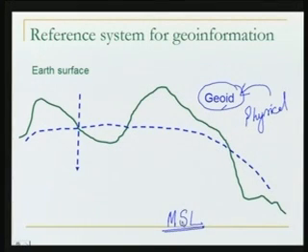So the average surface of the sea will represent a geoid. Everywhere the potential is same. Everywhere it is perpendicular to the direction of gravity. Now you can visualize this surface, isn't it? All over our earth, you can have a visualization of this surface, which we say the mean sea level. So the heights of these stations, the railway stations we are talking about, are referred from the mean sea level.